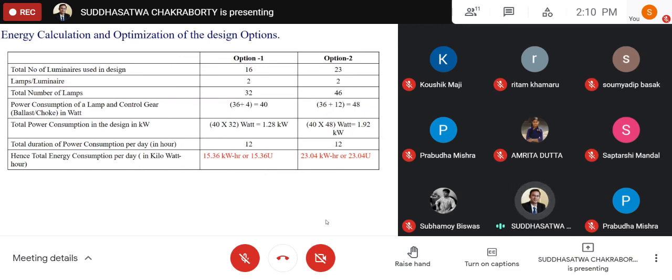But again and again I'm telling you, these lumen method-based calculations are accurate to some extent, but the reflected and inter-reflected lights, especially for the interior, are not accurately considered. So sometimes, for the sake of better calculation, we need to take the help of lighting design software. Those are mostly based upon an algorithm called Monte Carlo simulation. Monte Carlo is a very well-known method adapted to take care of infinite phenomena. The interreflection is an infinite phenomenon, so the Monte Carlo simulation will help us do that.